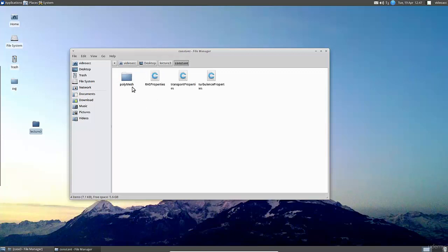In the constant folder, delete the mesh, because we're going to create our own mesh this time with Gmsh. It will be an unstructured triangular mesh. So delete this one. We won't be using blockMesh this time.